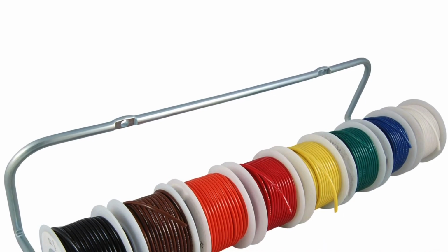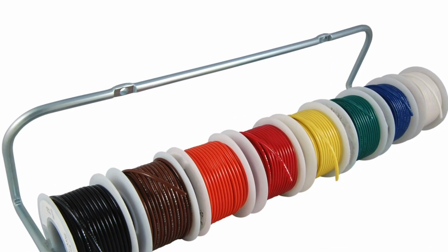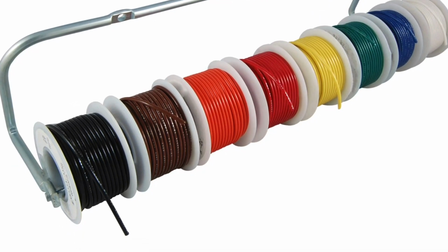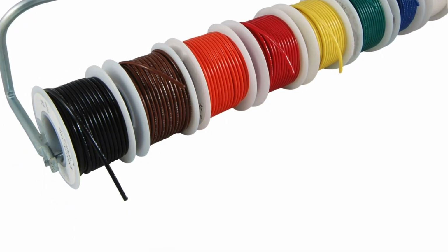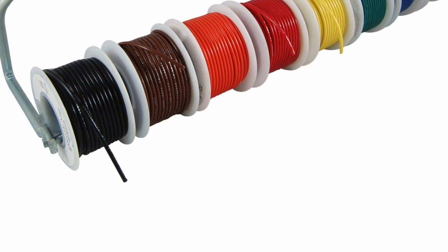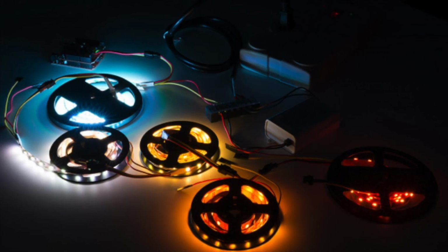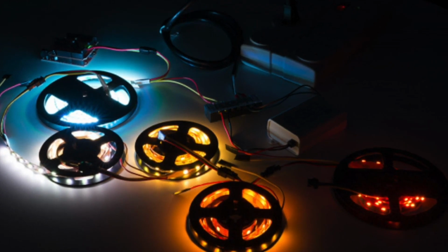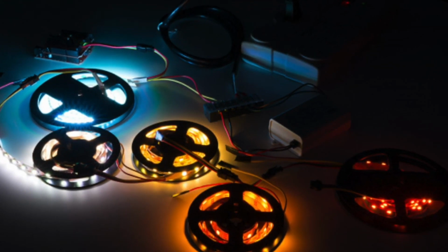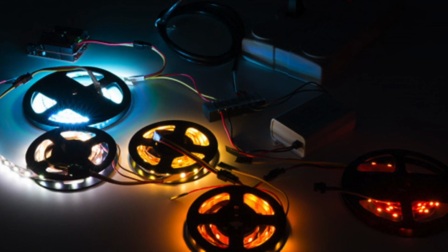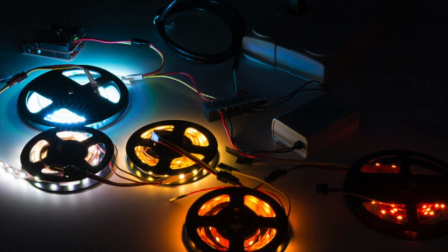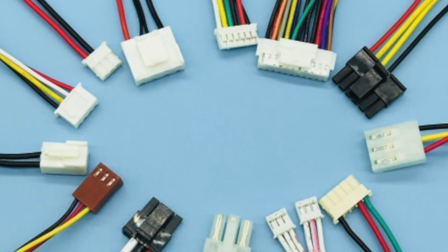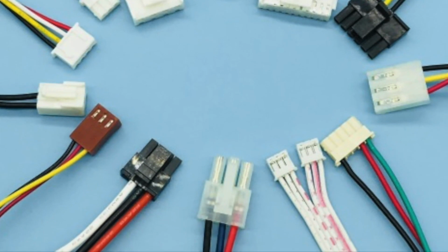Jacketed 16-2 hookup wire, available cheap from DigiKey or Mouser, is perfect for running wires from your power supply to your lights. It's best to keep this run as short as possible, within reason. If you can put the power supply within a few feet of your lights, you'll cut down on heat generation and voltage drop. It's surprisingly easy to run 5-volt lights down to nothingness, just from the length of the power cable. You can also add JSTs or Molex connectors to the power pads on your strip and your power cables to make them easy to disconnect.